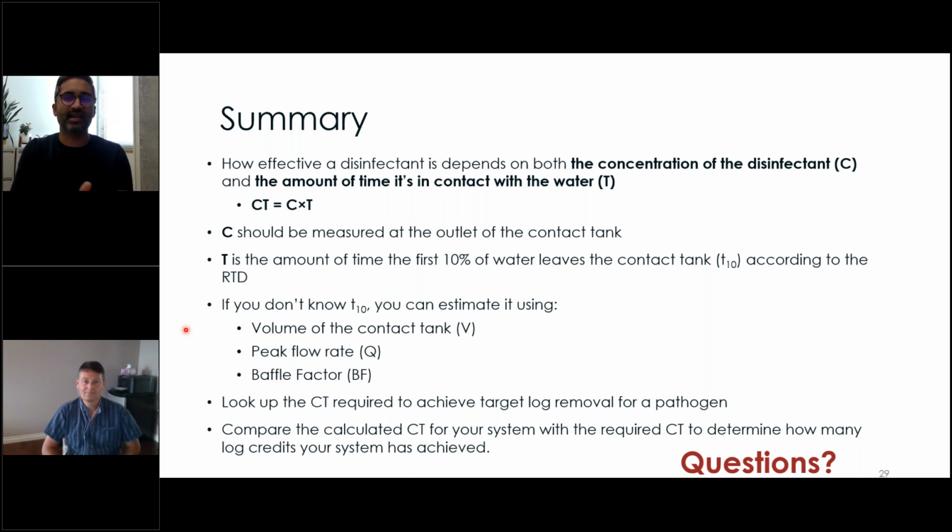You always want to tend to err on the side of caution when it comes to CT. As far as increasing chlorine dose, obviously there's limits to that. You want to be mindful about the residual that you're getting afterwards. So contact time might be the safer thing to try to increase, either through the use of baffles or adjusting your flow rate if you can. Because there's an upper limit to how much chlorine you want to be adding to ensure that you have a safe amount of residual going out to people's homes.